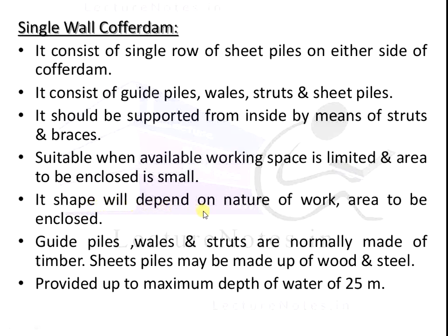Its shape will depend upon the nature of the work and the area to be enclosed. For this type of cofferdam, the shape depends on the nature of the work and also the area or site. The guide piles, wales, and struts are normally made of timber, and sheet piles may be made of wood or steel.